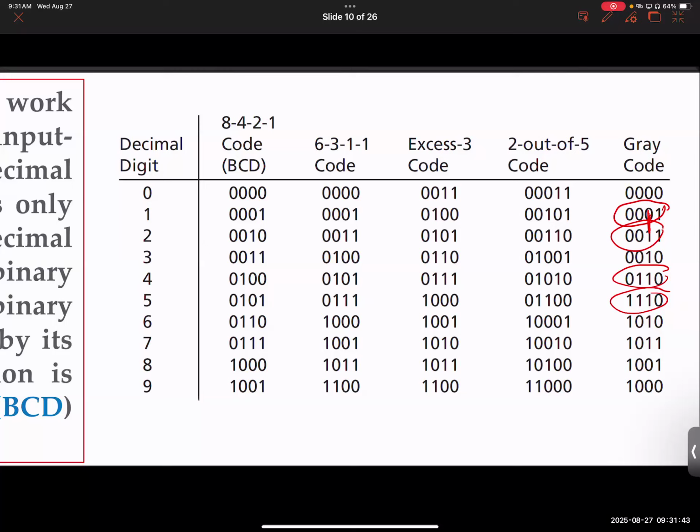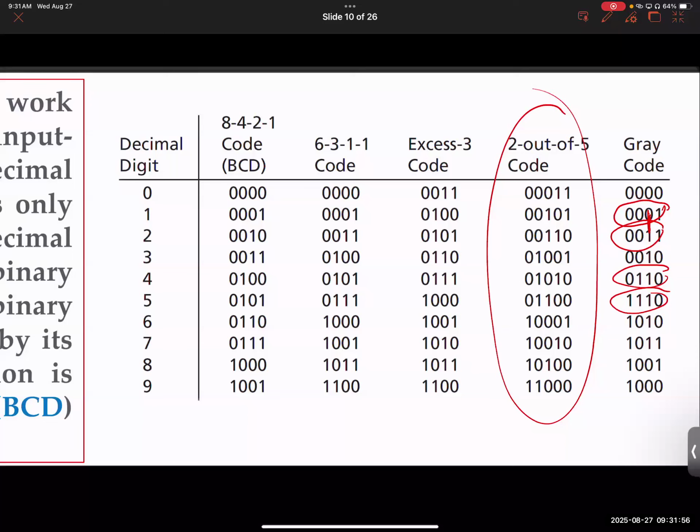So you can also come up with your own coding approach. Sometimes people have to go beyond 4 bits, as you see here, to 5, 6, 7. If you could justify a unique advantage of using 7 bits to represent these digits, sure, people will buy that. But without justifying something unique, we typically try to keep the bit count as small as possible. Remember, you have to store them somewhere. There is a memory block, and every bit will require its own memory. So that's why the smaller the better.